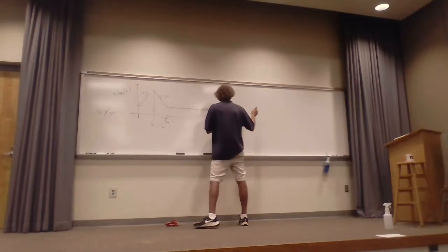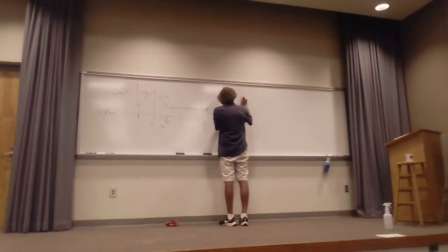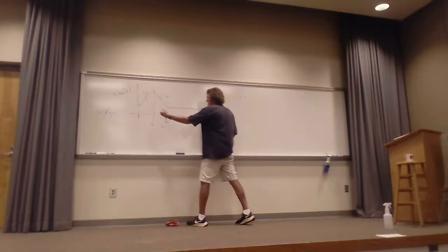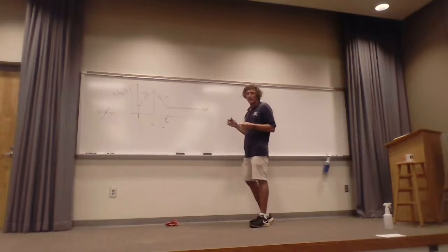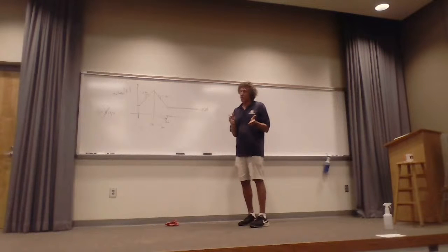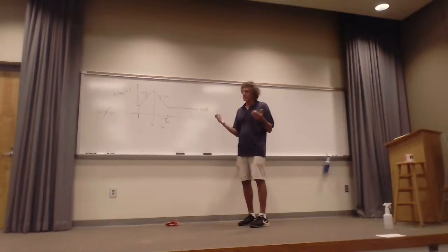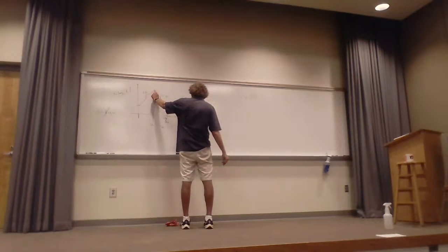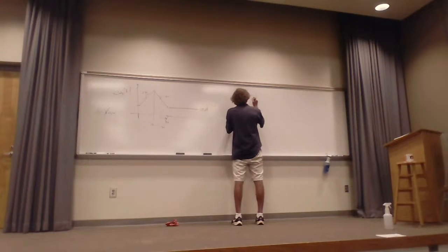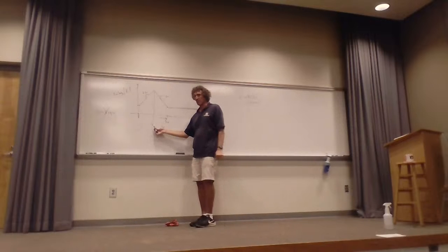Normally when we construct this function, we're going to put down Z. Just by looking, I start with a zero, and there is no start point in that, so I just put S here. No matter how low you go, if you add an order of magnitude to the frequency, you go up by an order of magnitude. With me on that? That's the linear coefficient you're going to use for this part, just S. Now, I hit a pole at 10, right? And by the way, you always put a constant there. So it's K times S. Then I have S plus 10 because of this pole, right?